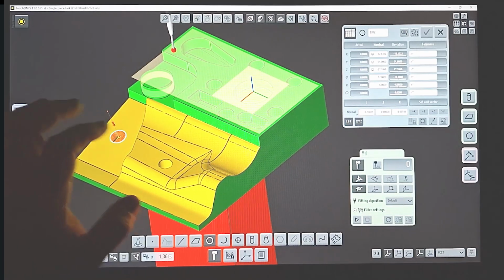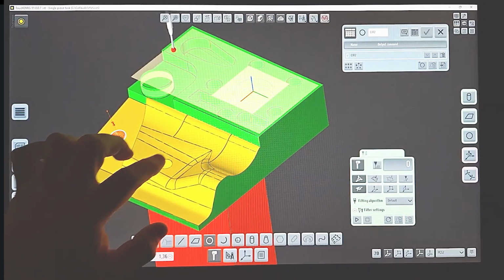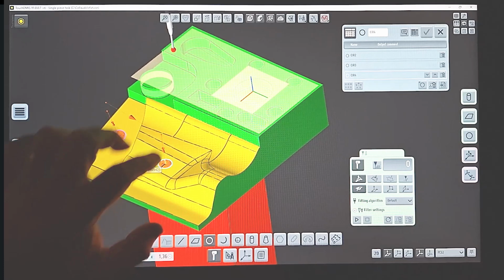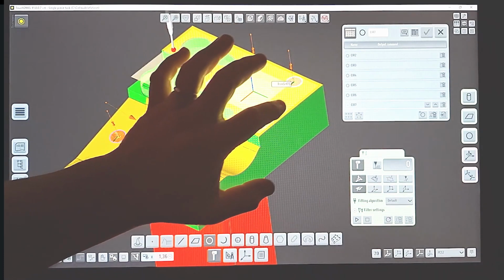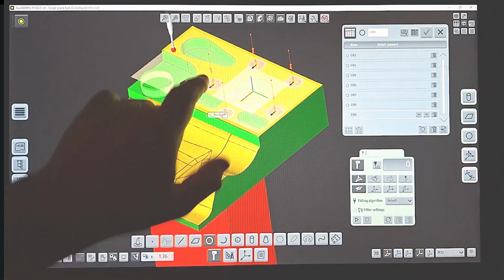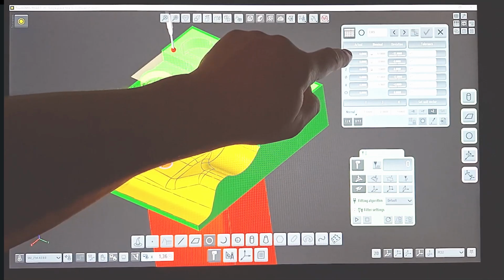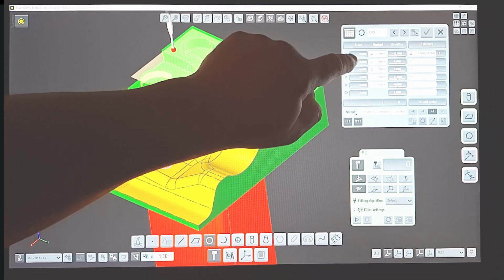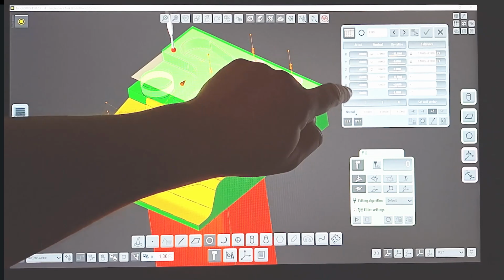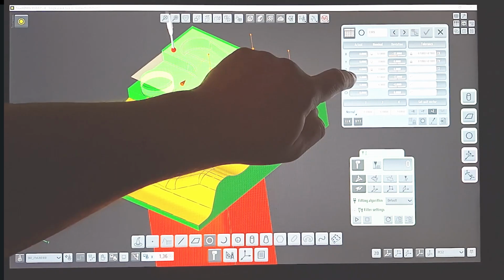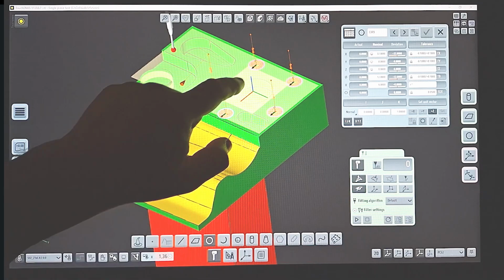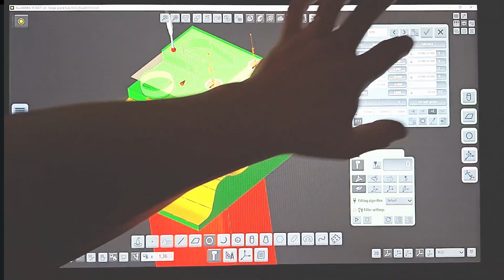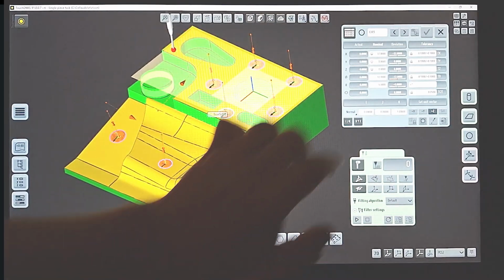Let's try now the multiple inspections. In TouchDMIS it is a very straightforward operation. We pick up from the CAD these elements. For all the selected elements, we want to have the X, Y, Z position, diameter, and form error. We also add these external circles and press play.